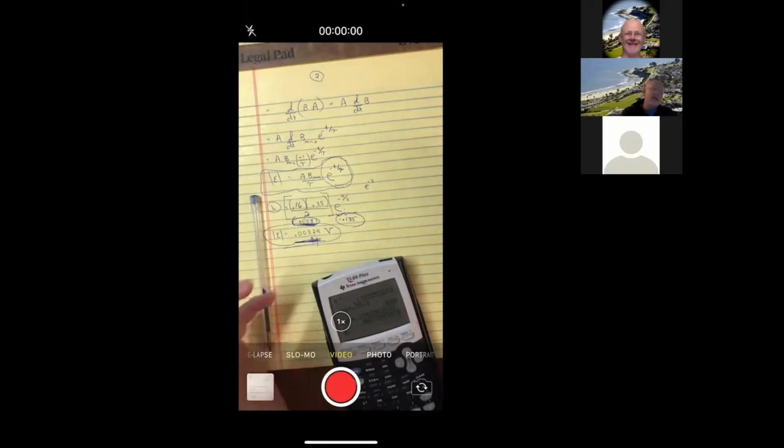But to disable the security device, when you're at the cash register, they scan it and put it on top of this, which looks like a little plastic pad. That pad has this big pulse that makes a strong field that decays away. That field is so strong that you get a strong enough voltage initially that makes enough current in that little security loop that it fries the security loop. The security loop actually burns up. Not so much that you see smoke or smell anything burning or see flames, but it burns up that loop, and that loop is no good anymore.